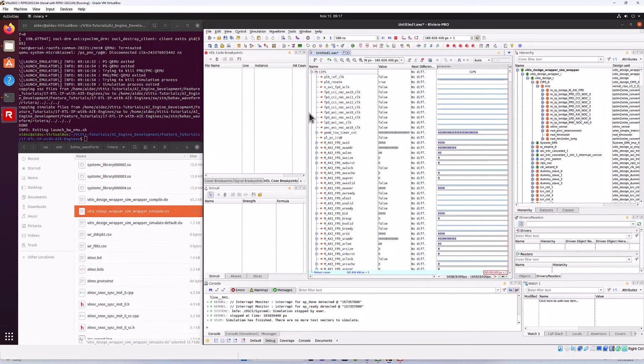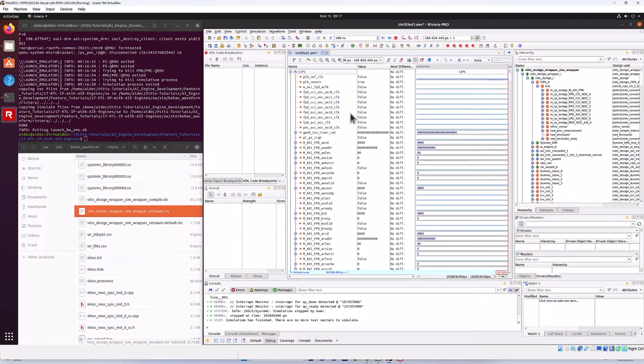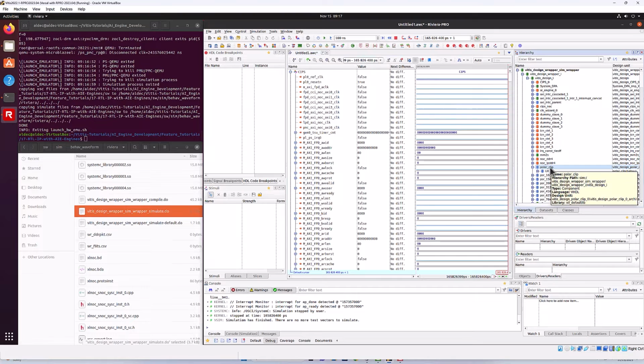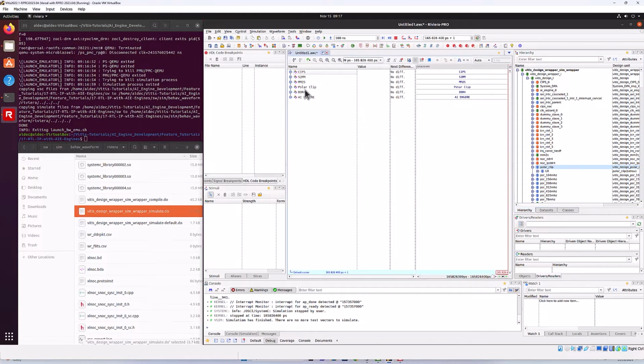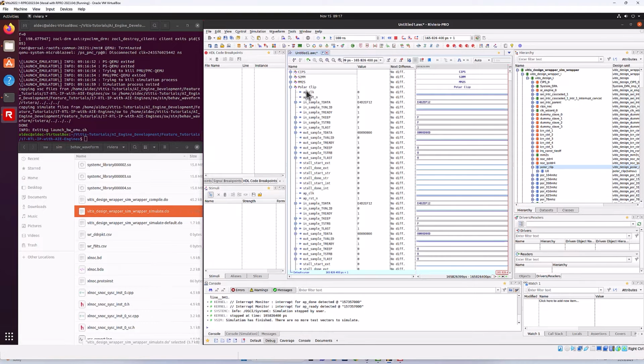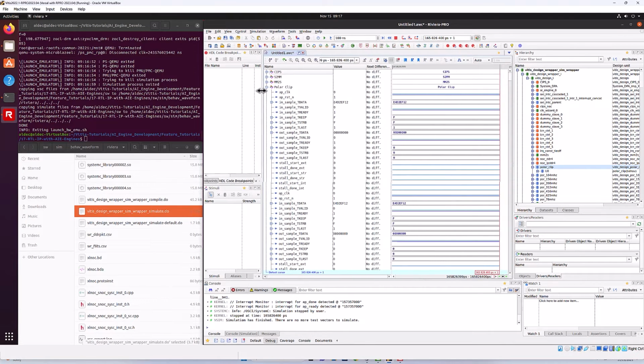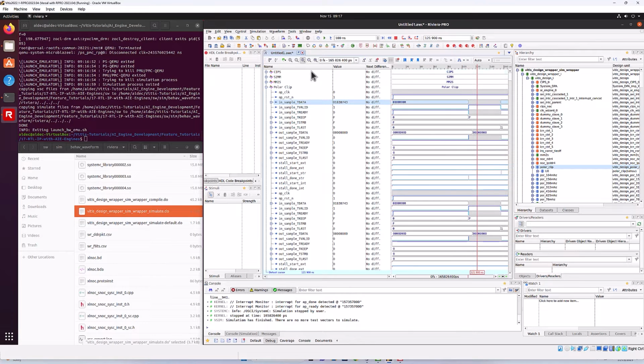So what I'd like to do in this next part is debug the Polar Clip. Okay, Polar Clip is the user RTL. Okay, so let's focus more on that design. Okay, all right. So here's the Polar Clip here. Here's the virtual group. Okay, and I want to focus the debugging in this in sample T data and out sample T data. Okay, so let's just take a look at this signal here. Let's go ahead and zoom to fit, and then let's zoom in some more.